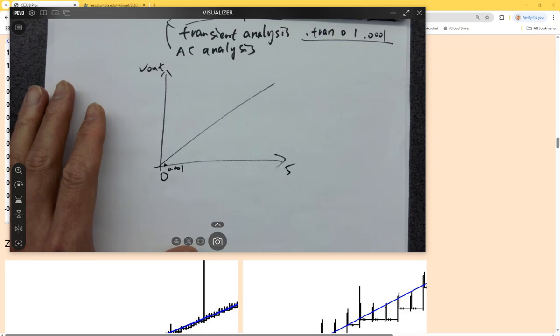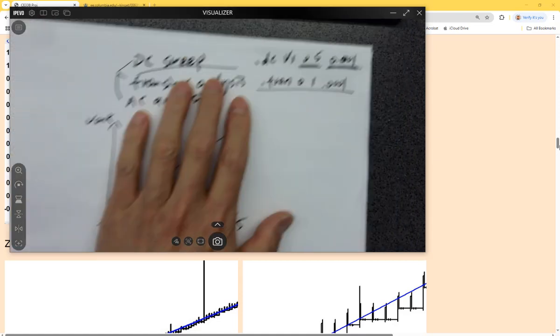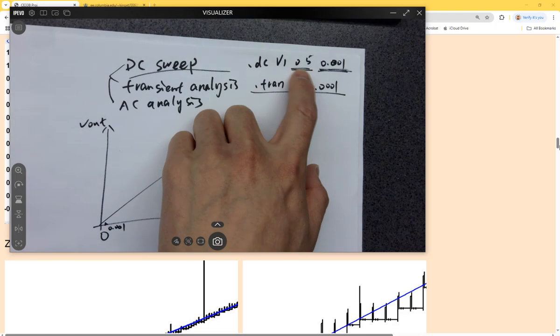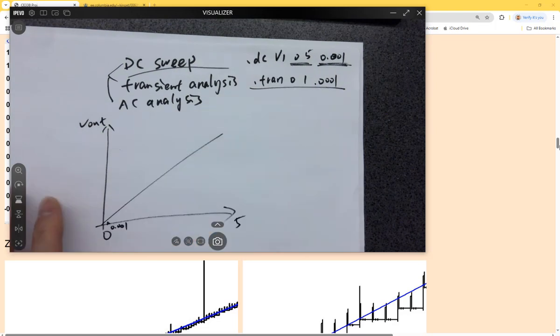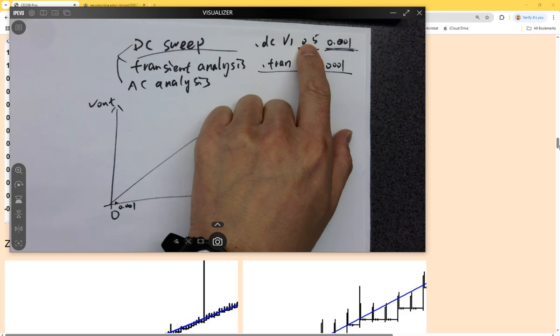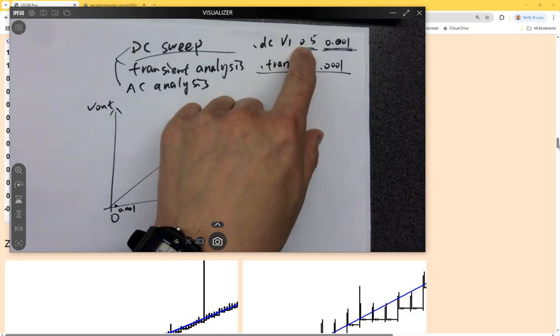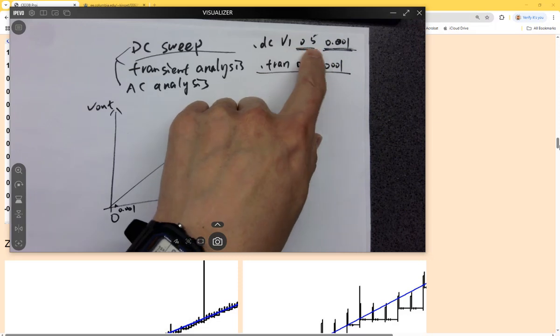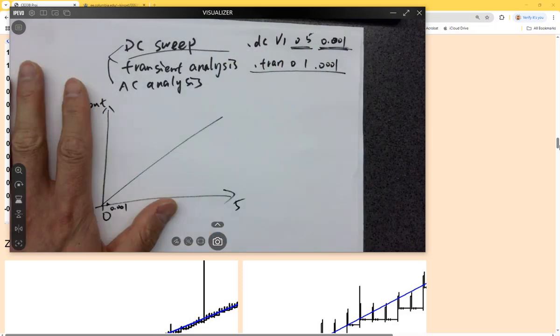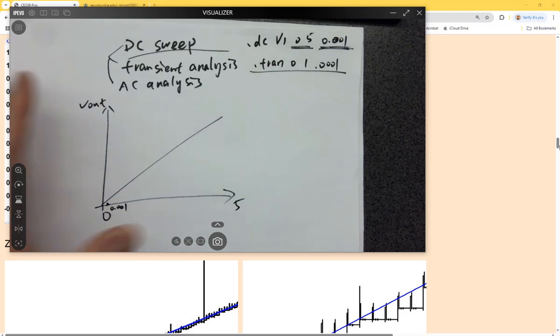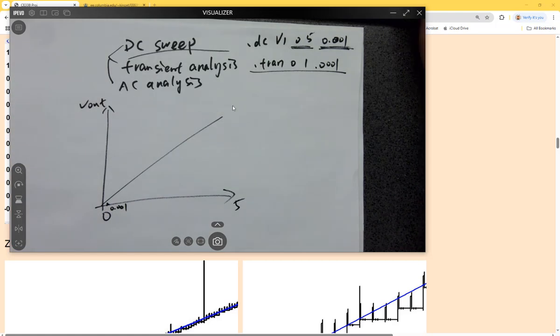Then you need time. But if I just do a DC sweep, there's no time. So that wouldn't work. Eventually, if you do a DC sweep on the ADC, you are getting a straight line. It's only taking the first point and giving you an output. It's not doing anything else, because the clock won't start. There's no time. So DC sweep doesn't work.